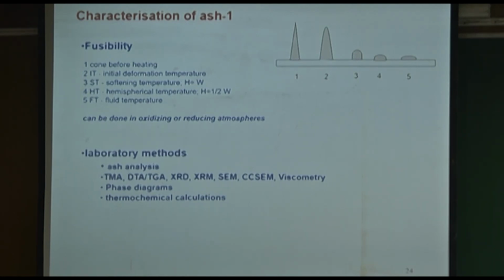Then you take the ash melted in the ash fusion temperature furnace or optical hot stage microscope, and run it in the X-ray diffraction. These days you also have high temperature X-ray diffraction. So you actually put the ash there, and the goniometer measures the diffraction pattern as the ash is heated. We have done that a fair bit. Not too complicated, not too easy. Interpretation of the diffractogram requires a bit of knowledge, but there are experts available in that area.